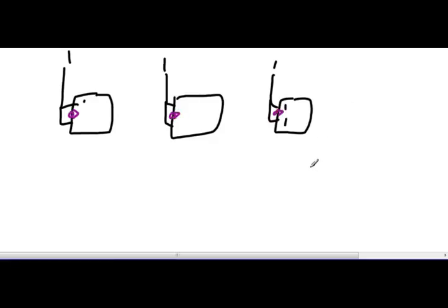I'm going to have a negative going clock, and I'm going to take Q and put it into my clock, and take Q and put it into my clock. And then I'm going to have a clock pulse coming in there. Okay, so I'm going to start at 0, 0, 0 again. And then I'm going to have the clock go down. All right, so the clock happened. I'm going to toggle 1.